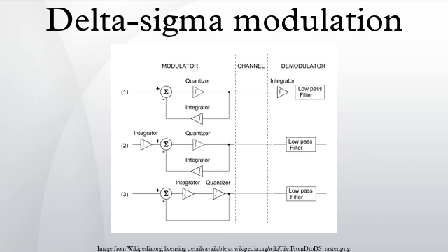From the first block diagram in Fig. A2, the integrator in the feedback path can be removed if the feedback is taken directly from the input to the low-pass filter. Hence, for delta modulation of the input signal, the low-pass filter sees the derivative of the signal. However, sigma delta modulation of the same input signal places the integral at the low-pass filter. In other words, SDM and DM swap the position of the integrator and quantizer. The net effect is a simpler implementation that has the added benefit of shaping the quantization noise away from signals of interest. This effect becomes more dramatic with increased oversampling, which allows for quantization noise to be somewhat programmable.